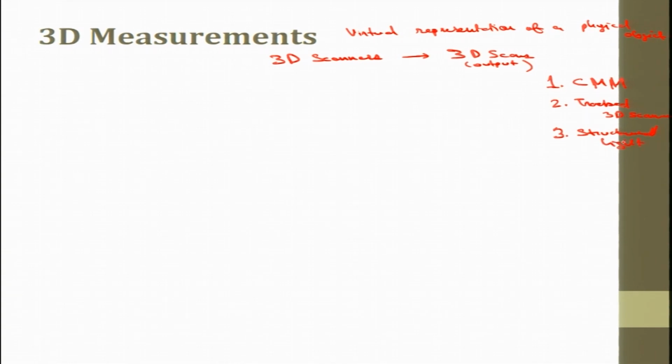Structured light scanner. By structured light I mean that these scanners project a pattern of light onto a part or a process while it is happening, and observe how the pattern is distorted when the light hits the object. Either an LCD projector or scanned or diffracted laser beams project the light pattern. One or two, or sometimes more, sensors record the projected pattern.